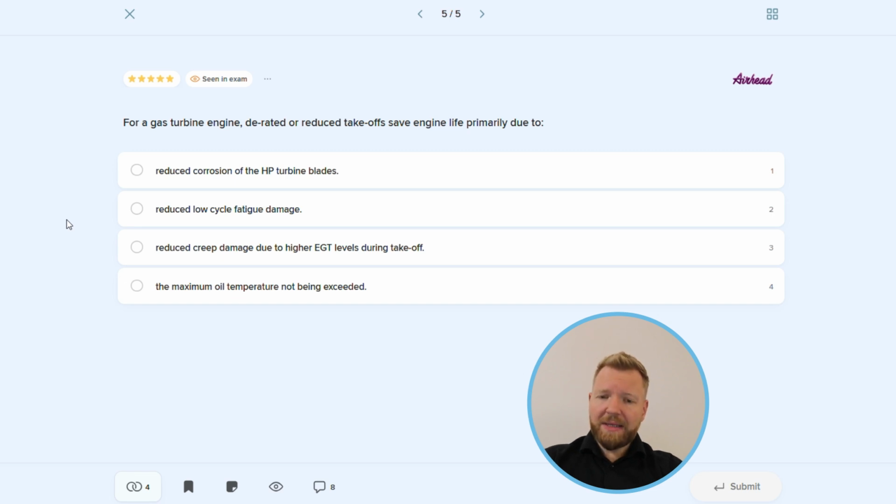The second method is a flex thrust, where pilot puts in the FMGS an assumed temperature, which has to be higher than actual one. In very simple words, in order to prevent turbine overheating, the engine software being tricked that the temperature outside is warmer than it actually is, will lower thrust for takeoff.